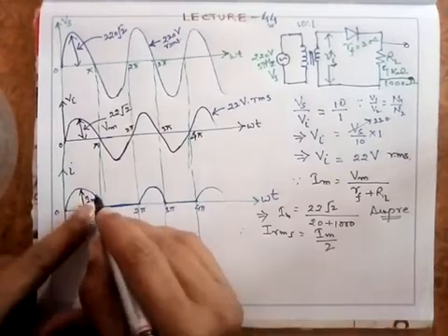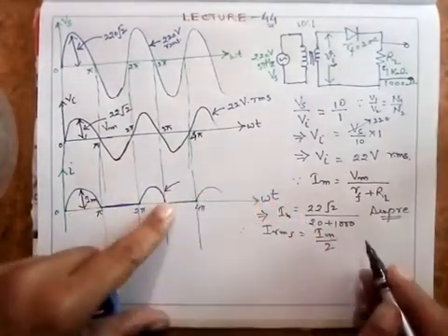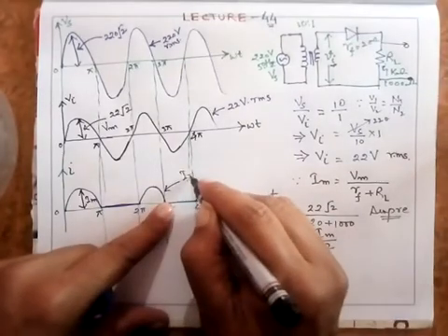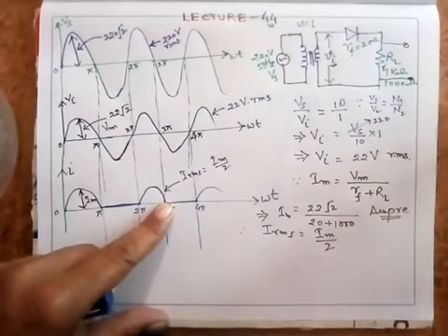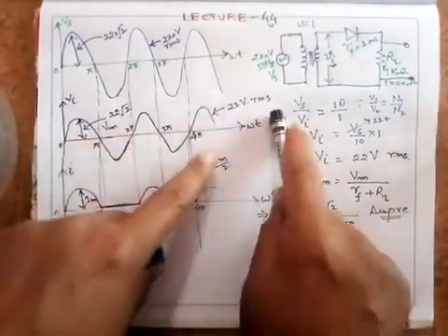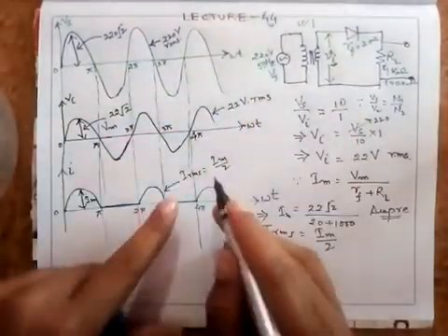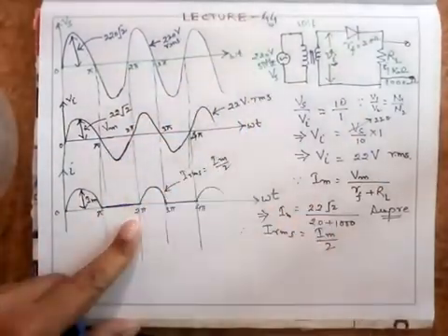IRMS, I am finding the RMS value of this. Remember, I say that the RMS value of this is equal to Im by 2. On the other hand, the RMS value of this is Vm upon root 2 or Im upon root 2. So I have derived the RMS value of this wave. It is pulsating, it has an AC component in it.